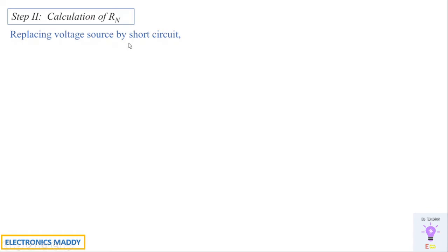That is according to our analogy. So we will be looking at this particular point because they've asked us to find with respect to the 2 ohm resistor, which was earlier in this place. Looking at this, the 1 ohm and 1 ohm resistors are connected in parallel, so you'll get 0.5 ohm when you simplify, and that effective combination will be in series with 1 ohm. You'll be getting 1.5 ohm as a whole.